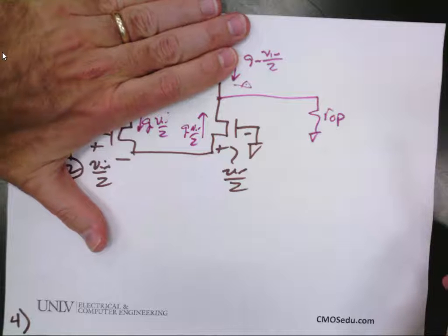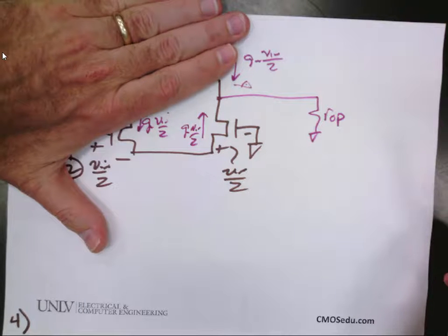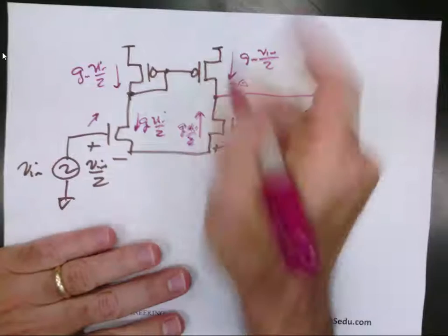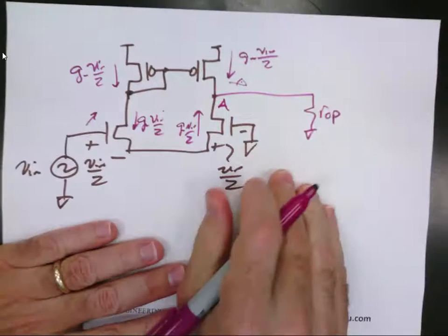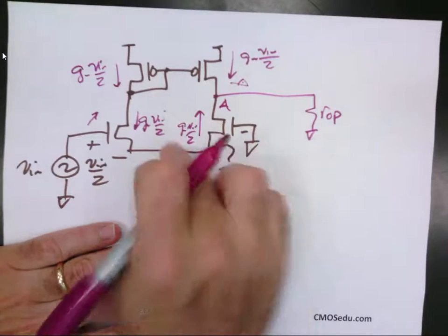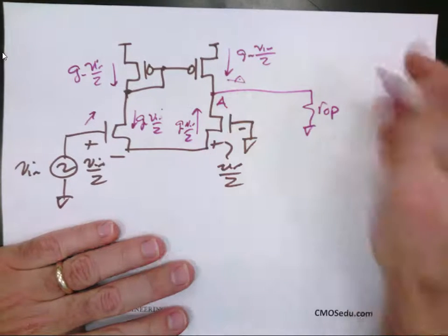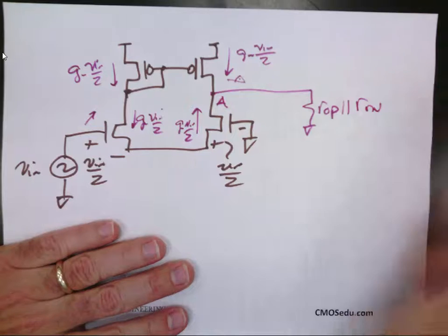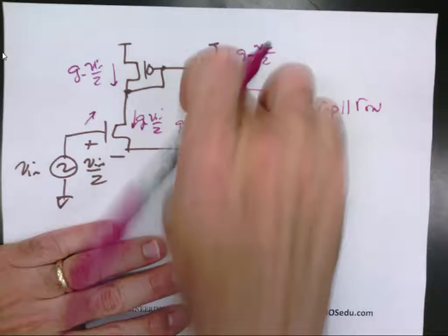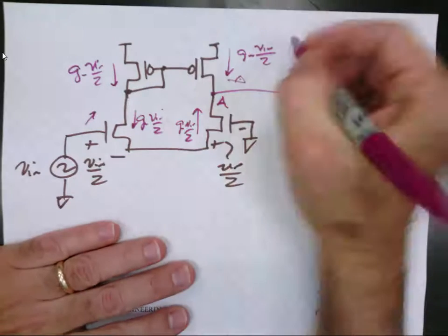See how I evolve when I learn to teach? If I ask what's a good estimate for the resistance looking down there, well, this is actually a pretty low impedance node, so I'm going to approximate the resistance looking down as RON. So ROP, RON, so the total current that flows here is what?